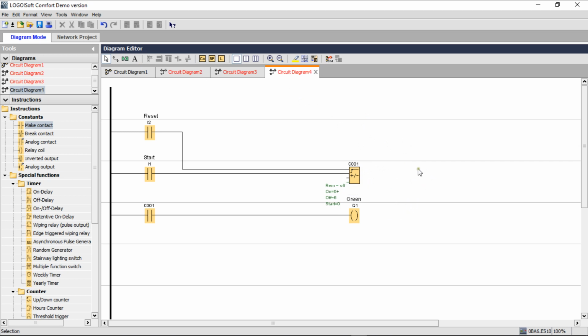When the direction is not powered, just like now, it will count up, acting as an up counter. But if your direction is powered, it will act as a down counter. If you are able to power and cut the power going to your direction, then you can make it an up-down counter.